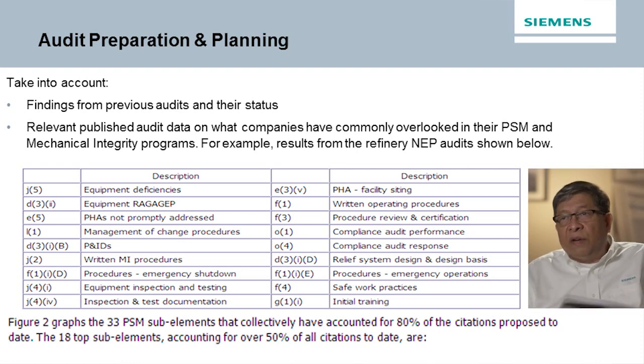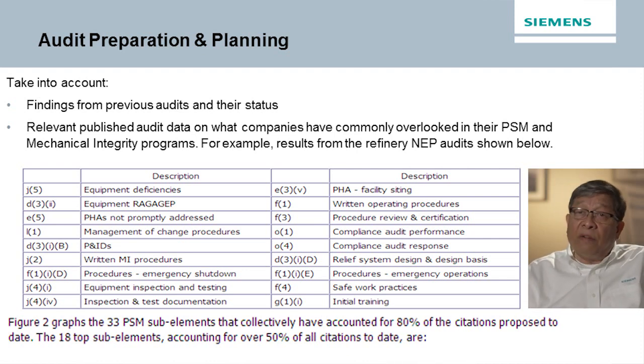And of course, the obvious violation is you don't have any written procedures, you don't have a written mechanical integrity program, you don't have inspection plans, checklists, and basis of your inspection scopes and frequency. These things need to be in place. So those are violations under J2.